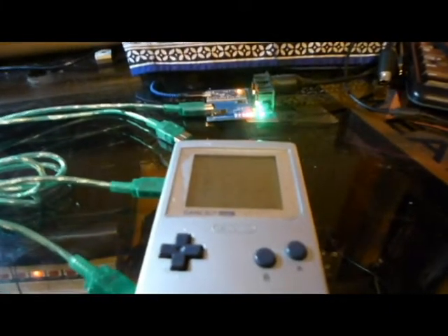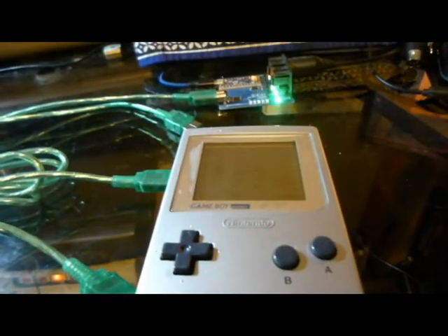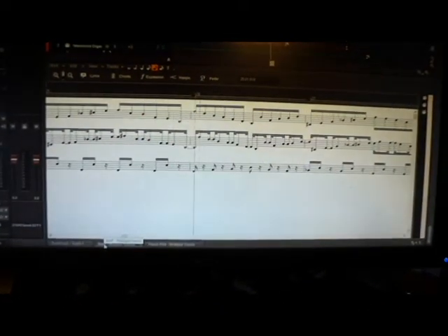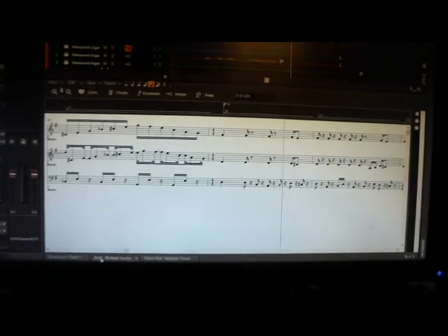And that is what the software I'm creating for the GenX is meant to do. It allows the GenX to act as a receiver of MIDI signals. It routes MIDI commands to whichever sound chips you choose, and allows you to assign which parameters of each chip are affected by which kinds of MIDI messages, if any. It's meant to be used in conjunction with a sequencer on a different system, probably your modern computer.